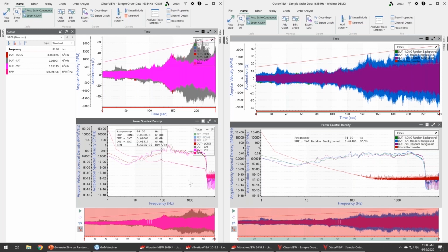So it's very difficult to figure out and isolate the sinusoidal content and really clearly define where those resonances are without smearing effects. So using an RPM sweep is going to be much cleaner, and it's going to result in a better application, or a better test in the end is the word I'm looking for.